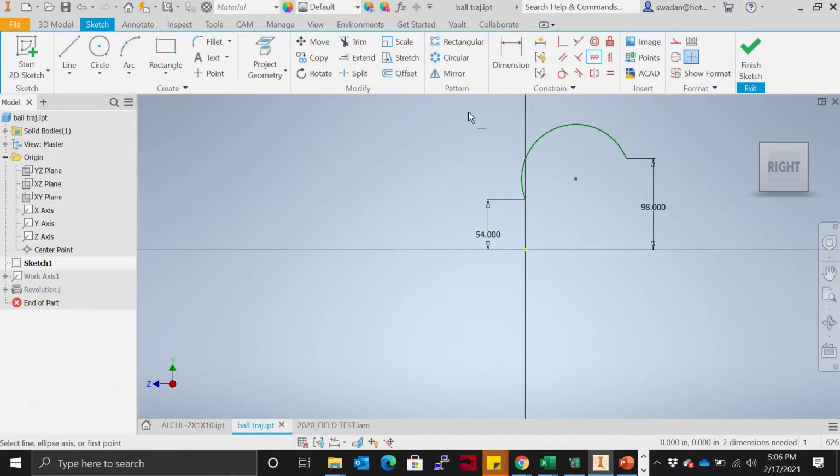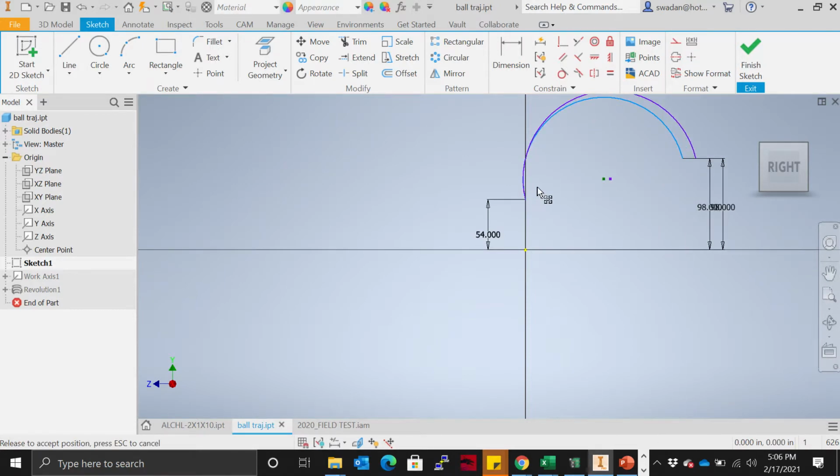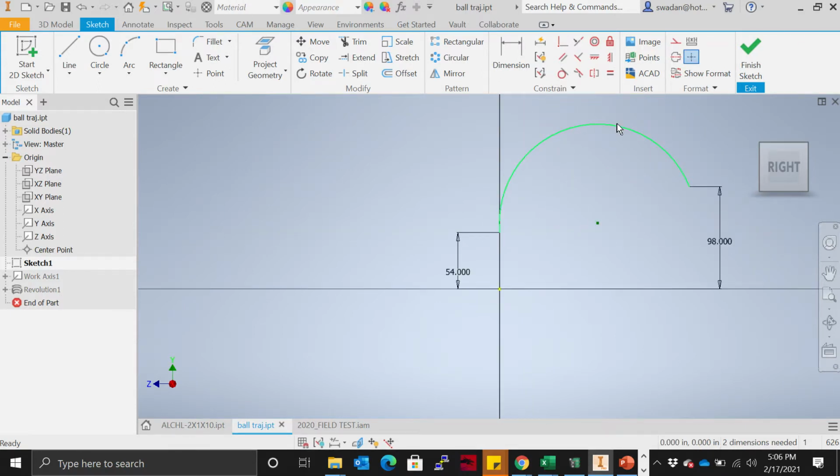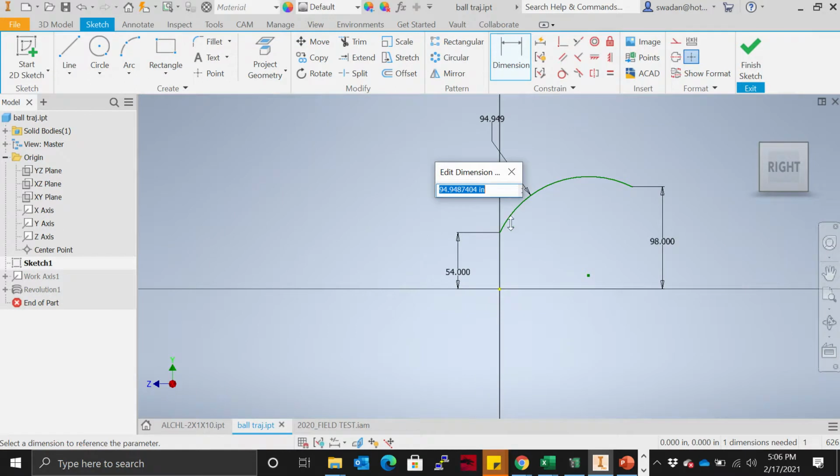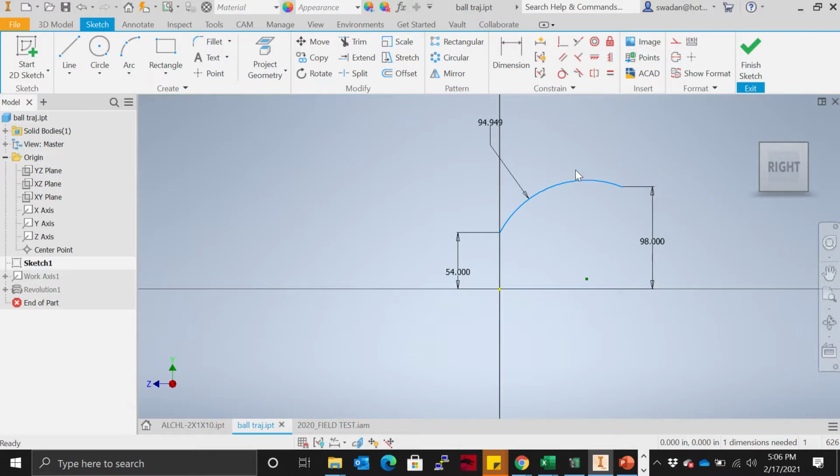So when you say you're constraining your dimensions, it means you're just trying to keep it on the 0 axis. Yeah, so one thing that's really important when you're doing CAD is, this is not good when you can just drag things. You want to be able to add as many constraints as you can to make it fully defined, to fully define what you're working on. Otherwise, you can be working on something and you'll just drag something, and then all of your very nicely calibrated measurements are going to be off.